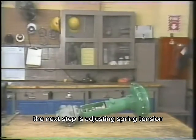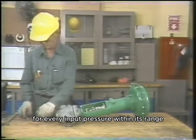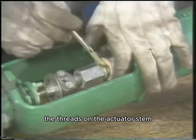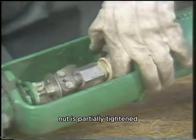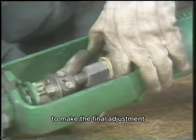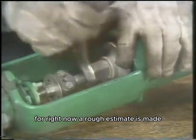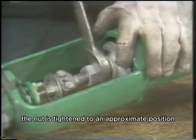The next step is adjusting spring tension to ensure that the position of the actuator will be correct for every input pressure within its range. To make the adjustment easy to do, it's a good idea to lubricate the threads on the actuator stem. Then the spring tension adjustment nut is partially tightened, so it begins to put some tension on the spring. To make the final adjustment, air pressure will be applied to the actuator and compared to stem travel. For right now, a rough estimate is made. The nut is tightened to an approximate position.